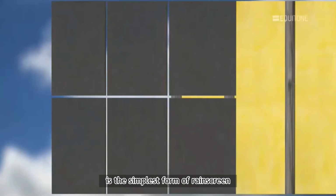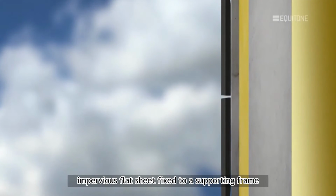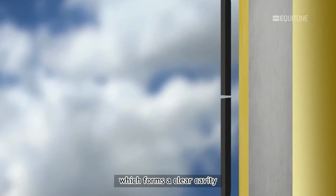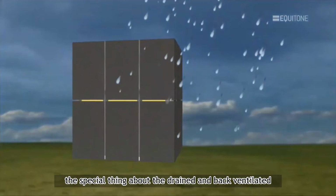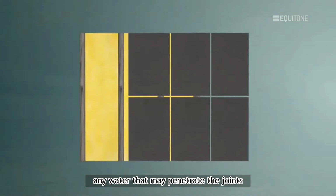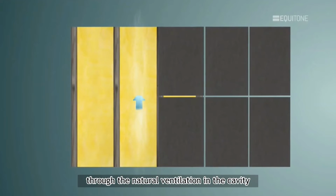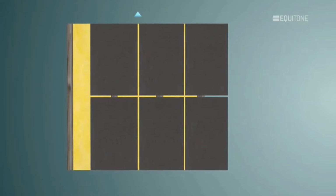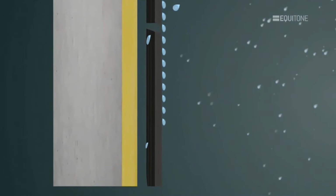The drained and back ventilated technique is the simplest form of rain screen and is favoured in Europe. It consists of a thin impervious flat sheet fixed to a supporting frame which forms a clear cavity between the panels and the insulation. The joints can be open or lightly baffled. The special thing about the drained and back ventilated approach is that the cladding is allowed to leak. Any water that may penetrate the joints and enter the cavity behind the cladding is quickly evaporated through the natural ventilation in the cavity or by draining down the back of the panels and out at the base of the wall.